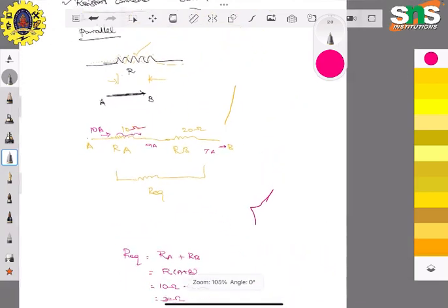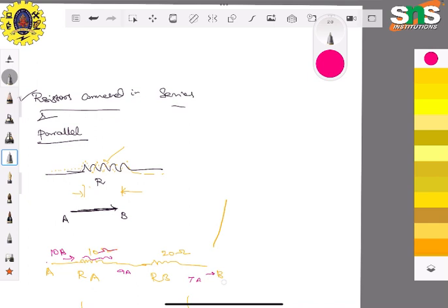Okay sir, where do we implement this kind of application of resistors connected in series? For example, in manufacturing we have different kinds of resistors, for example 2.2 ohm, 3.3 ohm, 5.6 ohm. These kinds of values are available. But if I need 31.27 ohm, I need to construct my own resistor. Resistors help to design a circuit with a desired value, but in the market we don't have that kind of desired value. That's why we need this resistance formula. Also, when we connect two or three loads in series, that value automatically gives the resultant resistance. Okay, so thank you.